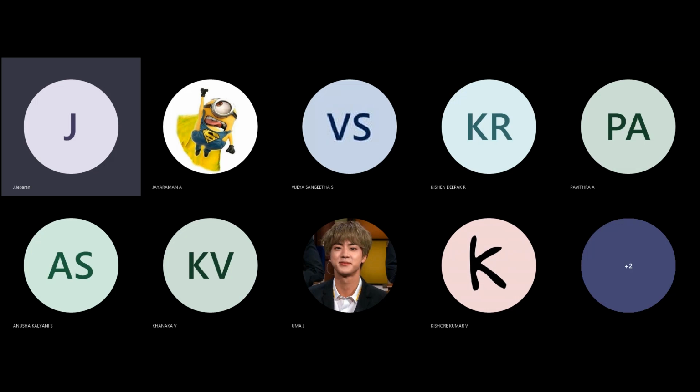A separate pin that opens in the mold for water injection. A valve at the end of the cavity opens a path from the main cavity into the second, overflow cavity. So the incoming water displaces the melt for hold and pack. It can be expelled through gravity and evaporation.